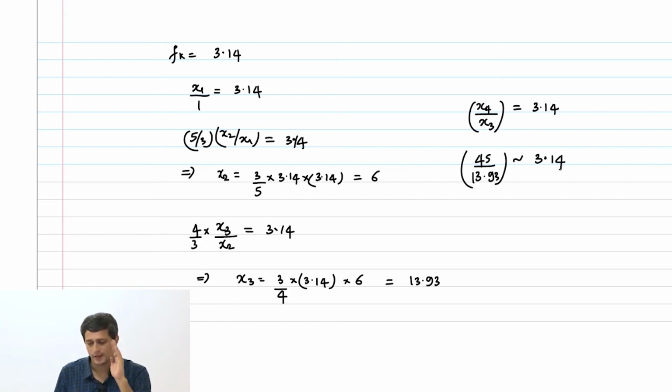Okay. Now the next step is to figure out what the size of your NMOS and PMOS transistors are. What we have found is the total input capacitance xk. We have solved for each of these things. I now have to divide this amongst my NMOS and PMOS transistors. Correct?